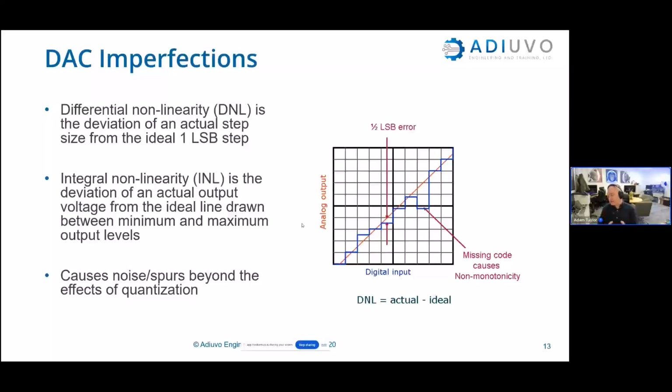So the quantized data, which appears in our processing chain, is going to put spurs and noise on the output of our signal processing, in addition to what we've already captured from the analog to digital, or from what our mathematics in the processing chain has added into the system. So we can have a lot of fun reading data sheets and trying to work all this out.